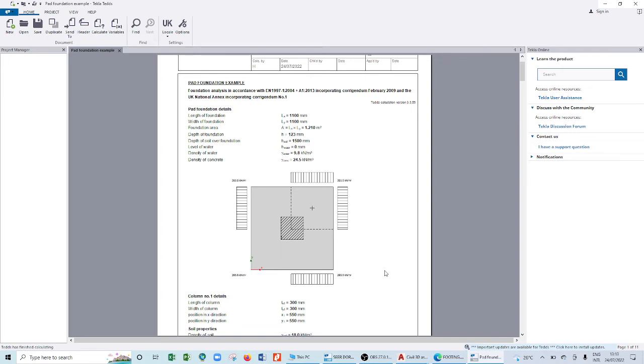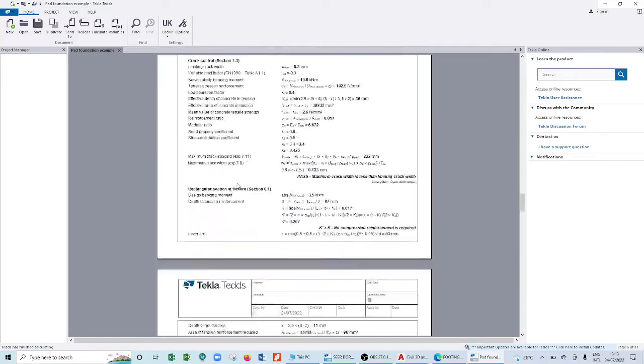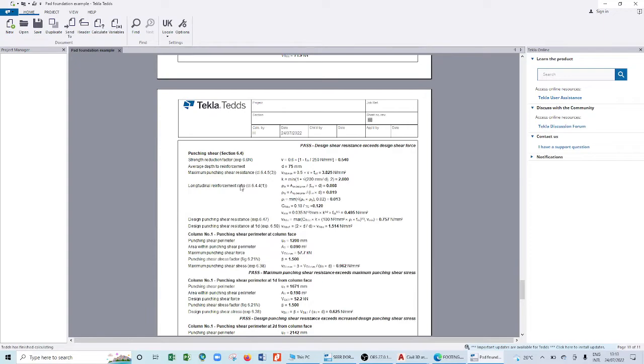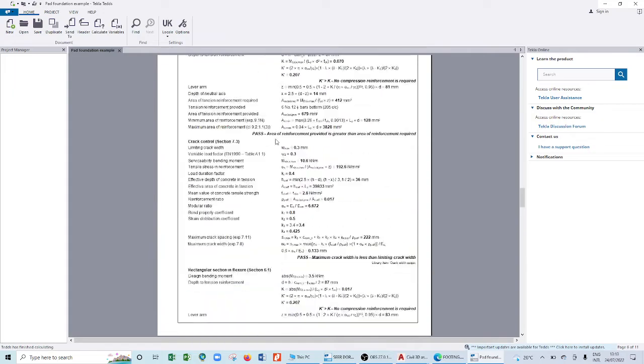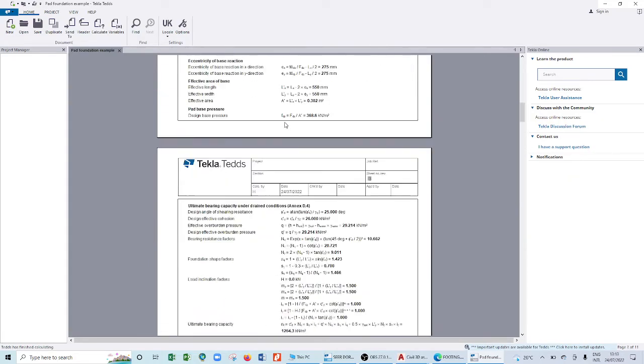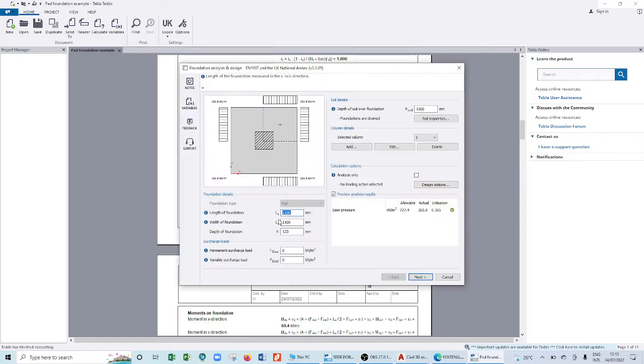Footing. Now, have we all got it right? Okay, now, once you're done with your footing, you extract the value that you want. The size of footing we are going to use, it's going to be 1.1 by 1.1. Then the depth, you can take a minimum of 200 or what you have in your design here.